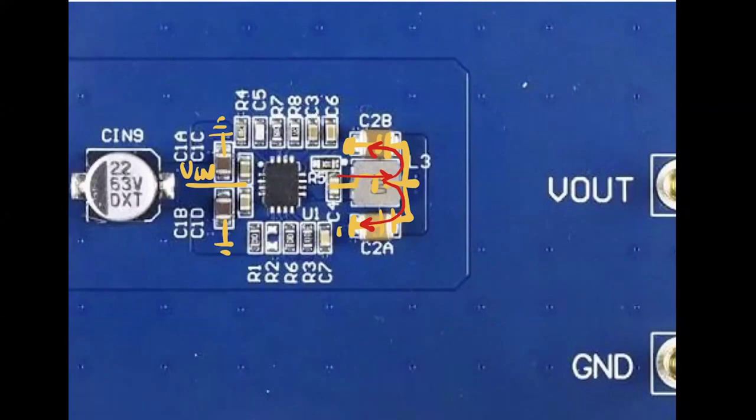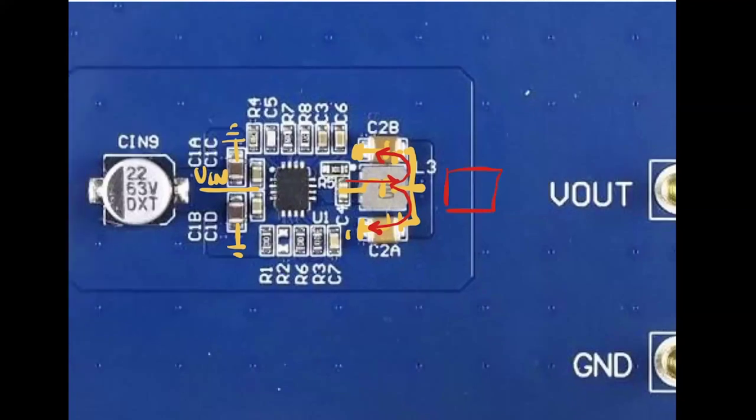And additionally, the idea is that this capacitor and this capacitor close to the inductor creates some kind of shielding of the inductor. So the 2 capacitors close to the inductors create this shielding. So anyway, if you put the inductor in this position and you put the capacitors in this orientation, you will get some cancellation in the same way. So it's correct, but you will not get the shielding effect of the capacitors with the inductor. So both situations can be good. I prefer the one you have in the MPS board, but the other placement is correct too. Okay.